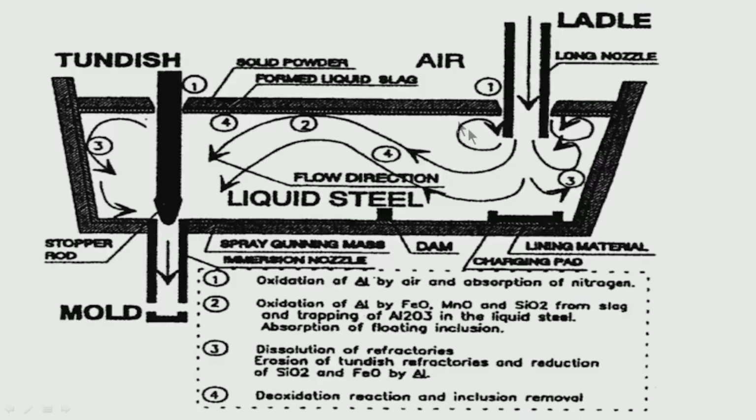So, this is important. The slag constituent, what will be the slag, that is very important. Next, what is happening here? Liquid steel is there, there is a continuous flow. So, at this point, that means the refractories should not get eroded here, should not react with the liquid steel. So, at this point, here also